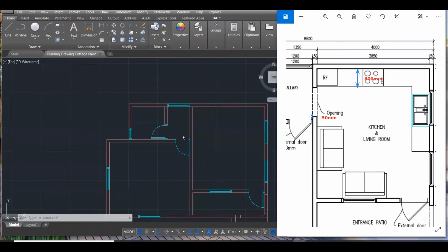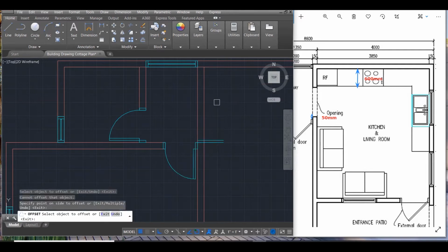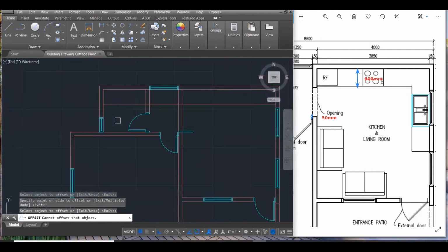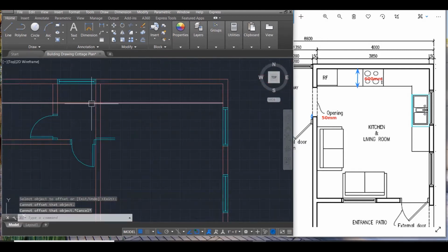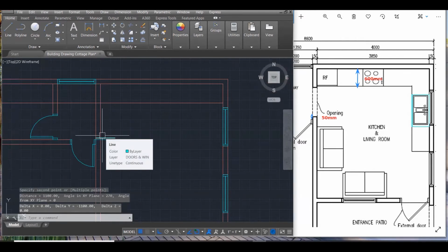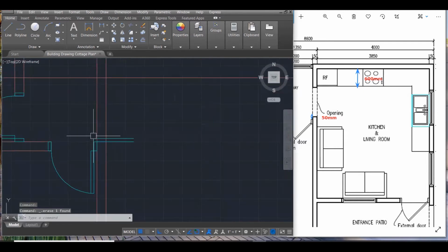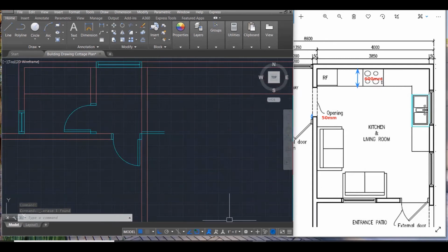So let us proceed. So I come here, draw a horizontal line, offset 50. That's in place, and then from here offset 600. Yeah. Then let's see how much I have left back. I have something like 1100. You know what? I'll make it 1000. So I'm going to offset this out 100 more. Give more space to the counter and make that opening 1000 there. So I actually offset that 700 rather than 600.